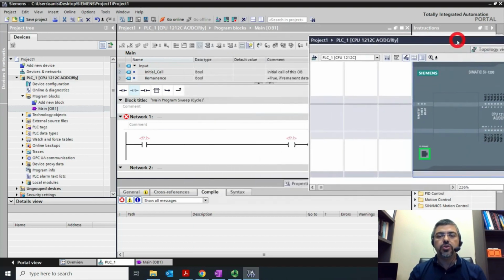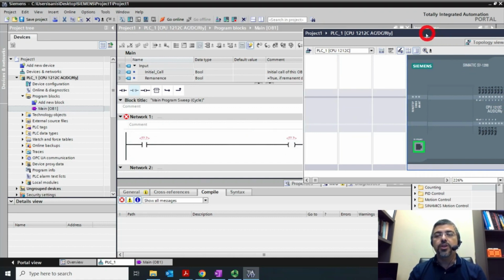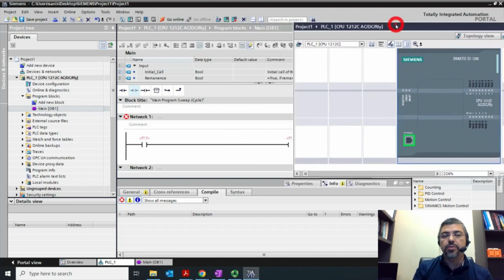Now definitely you should specify something. This is the input, right? I mentioned the power comes from left to right, so the inputs, which are the contactors, are on the left and the output is on the right side. But here you should say which of these contactors connect to which inputs. You have these options, 0 to 7. Same for the output, which is your coil. All these options are here. So you should definitely set one specific input and output.